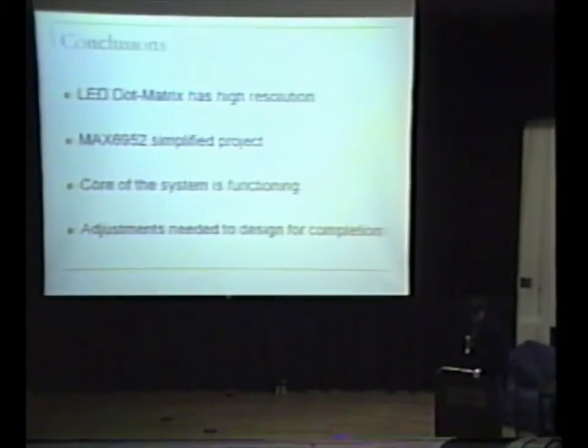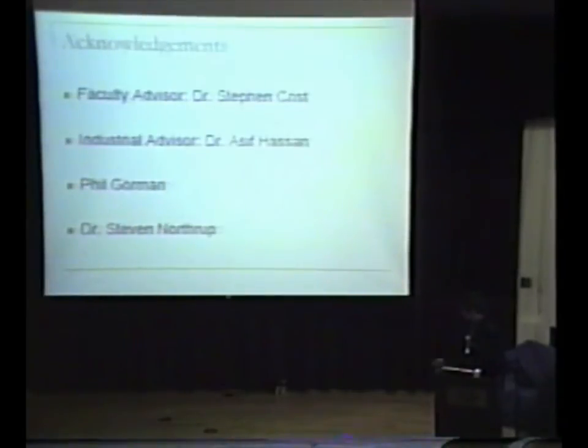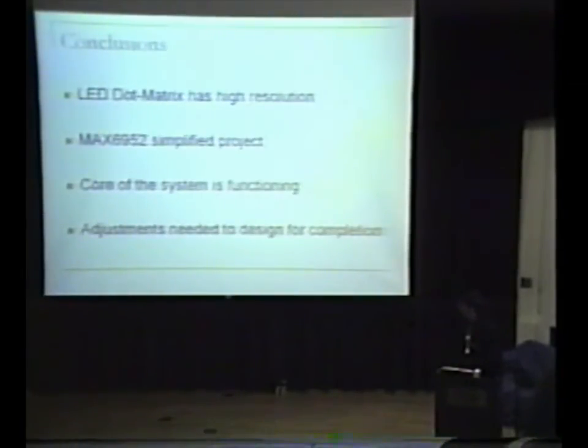In conclusion, the LED dot matrix provides a higher resolution. The MAX 6952 simplified the project by providing any necessary time multiplexing. The core of the system is functional, and with a few adjustments, the design can be completed.